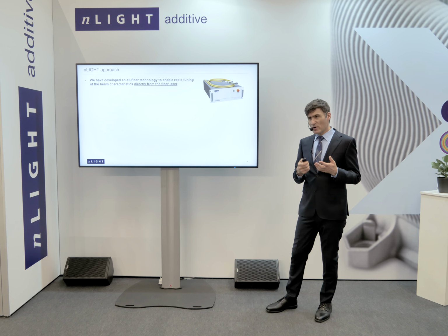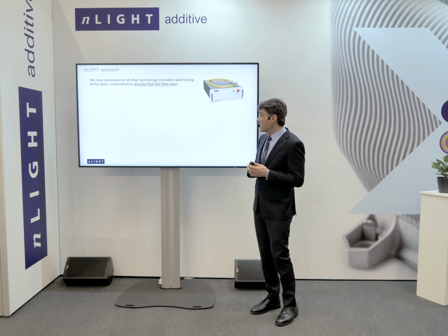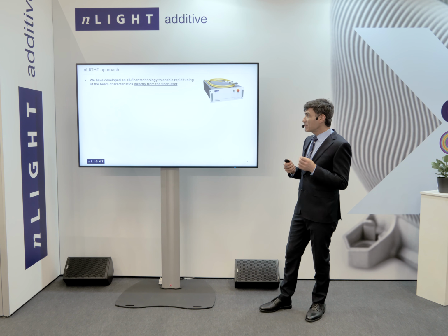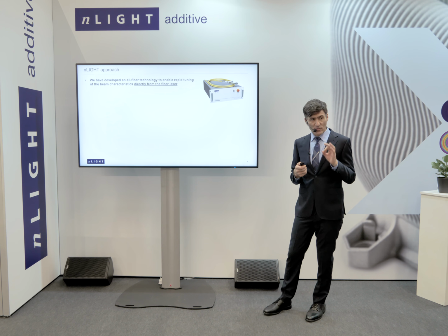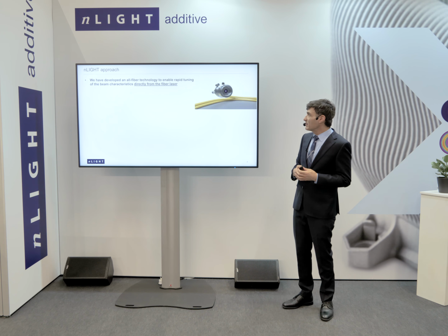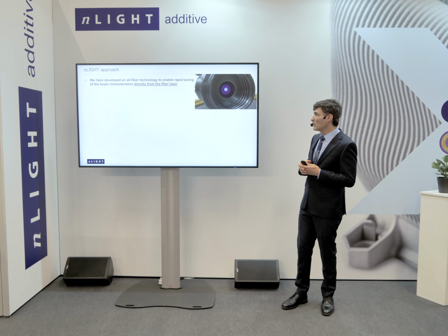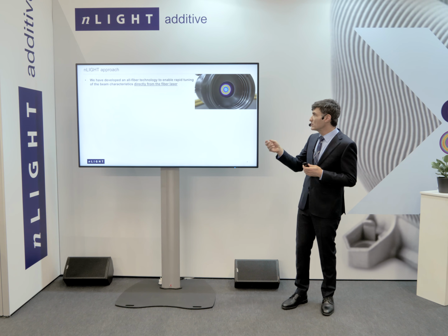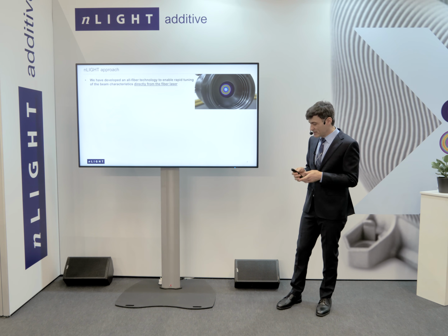So that's really what motivated us to take a fresh look at the problem and develop a new approach, and that's the Afx Fiber Laser, where we can rapidly tune the beam characteristics directly from the fiber laser, right out of the delivery fiber, as shown here. These are actually CMOS camera images of an actual 1 kilowatt beam, and it's switching between the single mode shape that I showed you to the 40 micron ring out here and shapes in between.